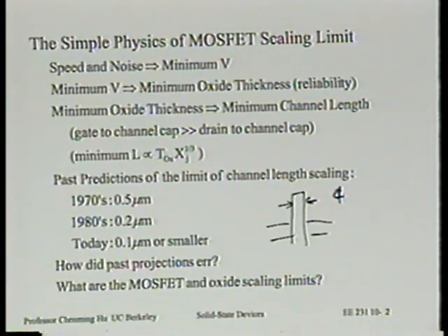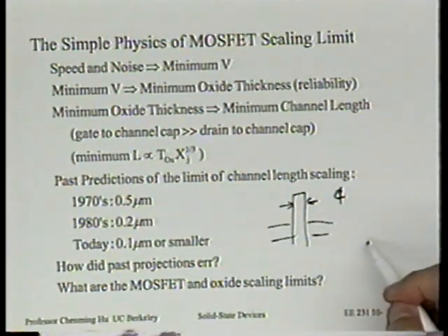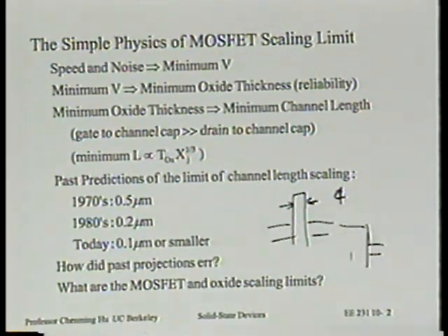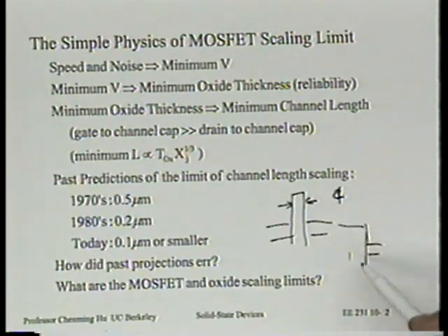You know, when I was a student, professors always taught us there's a layer of SiOx at the interface of silicon and oxide. We don't know what it is. Let's not even go there. Don't touch it. It's terrible material. That's why we need 1,000 angstrom of SiO2 to get good properties. And we don't know what junk is at its interface. It's a transition region, right?